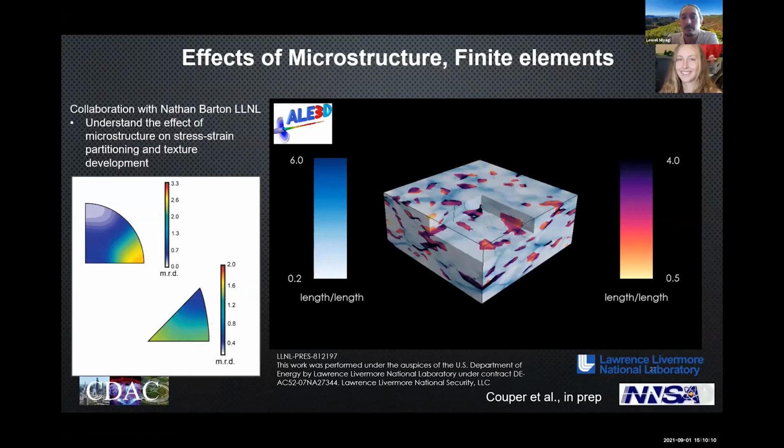Oh, are you talking about something like here? Oh, yeah. Yeah, and I would guess this is partly geometry. So this is a confined axial compression, right? Yeah. So we can change the boundary conditions, and this is also only about 40% strain, right? So we're trying to mimic what we can achieve in the diamond anvil cell. So you can kind of get a hint here where you see some of these things starting to elongate. They're not quite interconnecting, but you start to see this. So I think potentially you can do a larger strain, right? It's computationally expensive to do a larger strain, right?